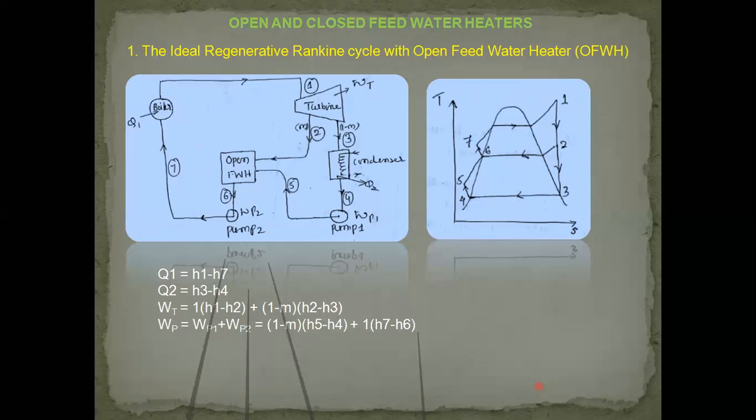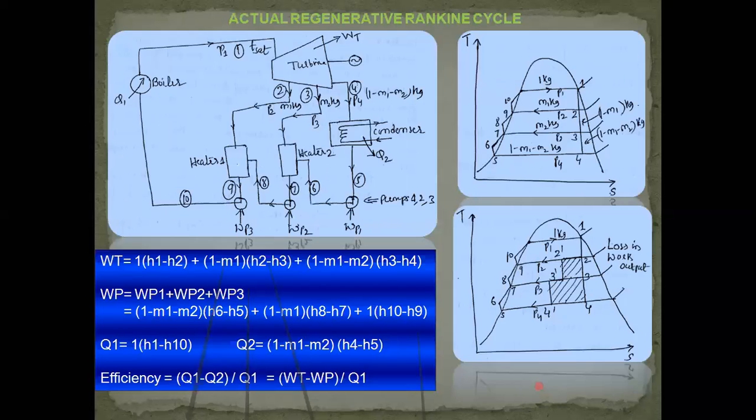These are nothing but heaters in which the water that comes out of the pump after the condenser must be heated up before entry into the boiler. So that is by way of regeneration. The input water into the boiler must be heated by some means, and that means is very much clear from this turbine in regenerative cycles, as we have seen in the earlier class.